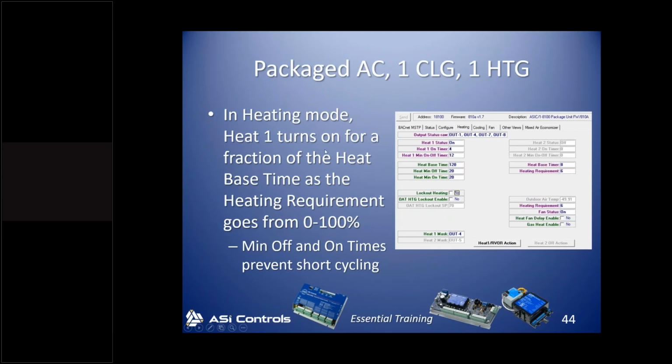And so heating, there's a separate heating tab for the AC personalities. The settings have similar functions. They just happen to be shorter, as if this was kind of electric heat. And so these are the default base times. You can certainly change them, but we'll turn on for a fraction of the heat base time according to the heating requirement. And then we have minimum on and off times.